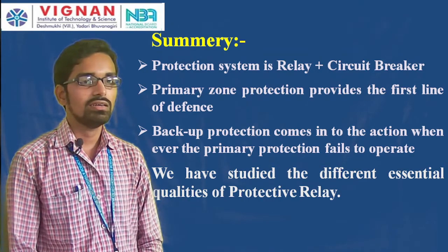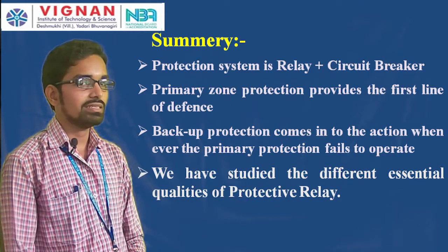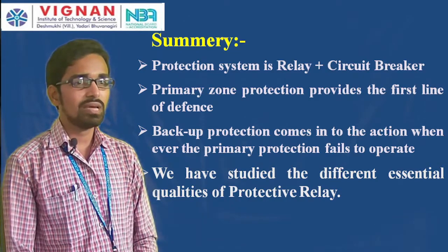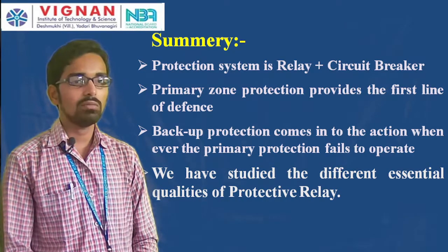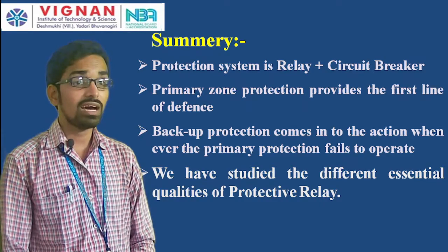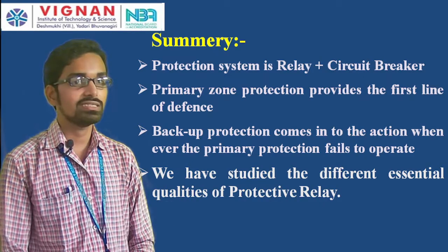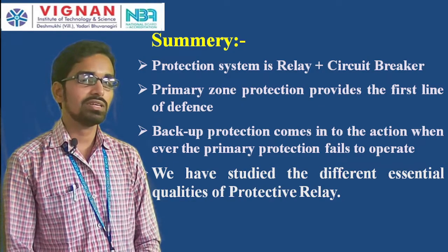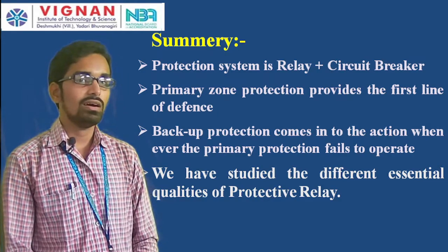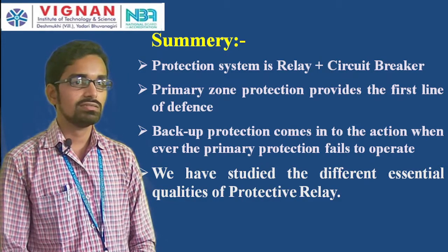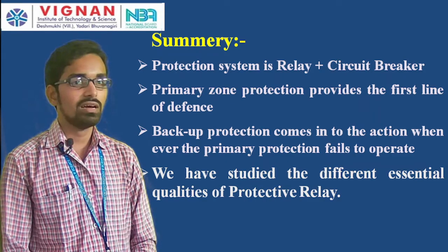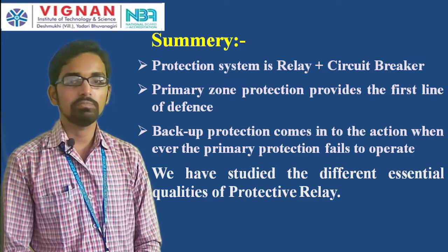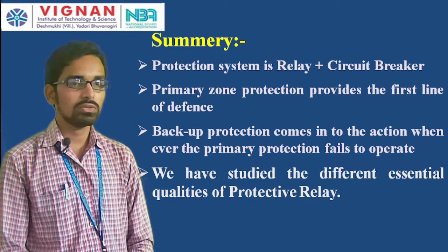Backup protection operation is unavoidable in providing protection, but its operation will disconnect a larger number of loads. As we have to provide continuity of supply to the consumers, we should not have disconnection of the supply for the consumers. We have to give utmost priority to the primary protection only, which will disconnect only a small portion of the loads.